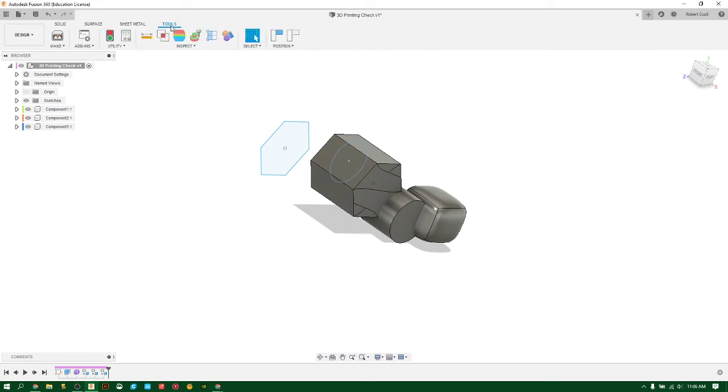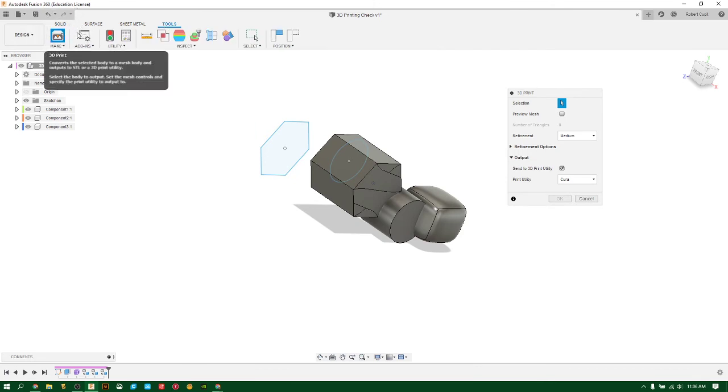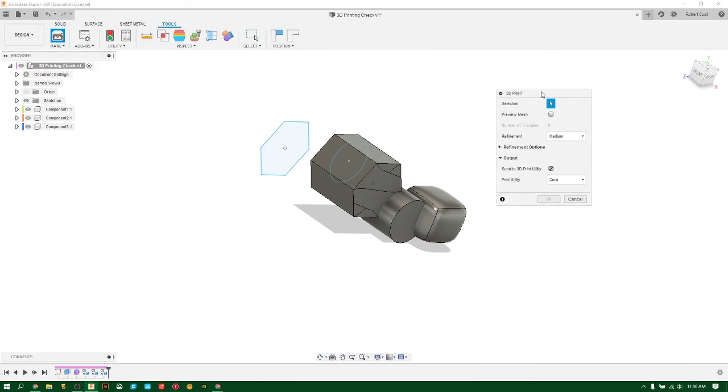If I go through Tools and I go to 3D print, and again, I never showed you any of this. Tools is up here. 3D printer is right there. You press that, it'll bring open this prompt box. You basically then select the objects. Well, if I hold Shift and try and select multiple objects, it doesn't do it. It ain't working. So we have to cancel that, and we have to create what's called a selection set. I've never taught you this either.